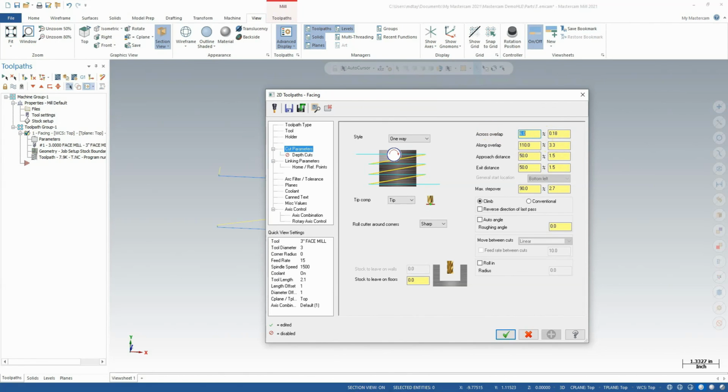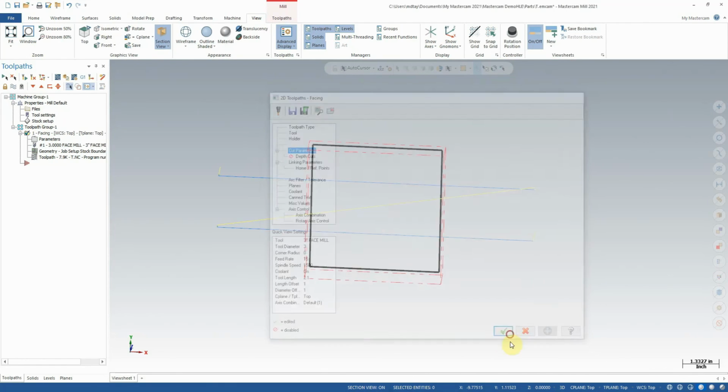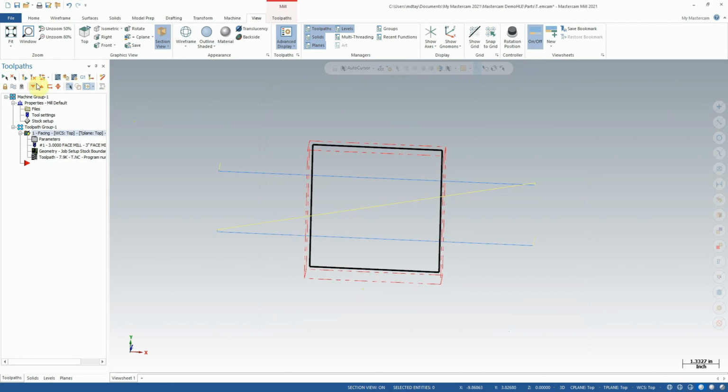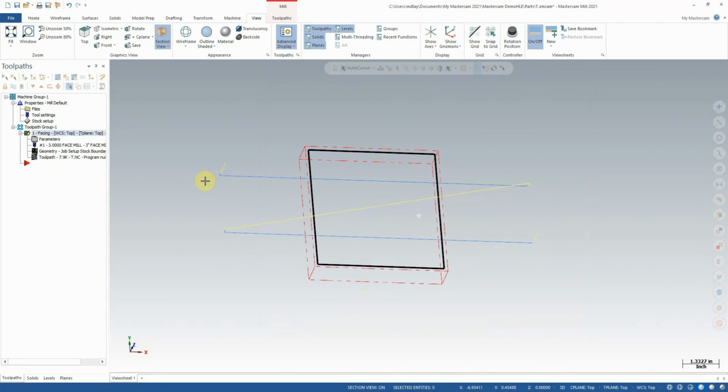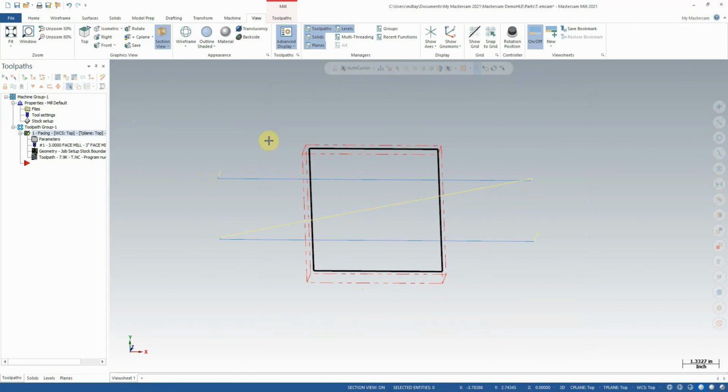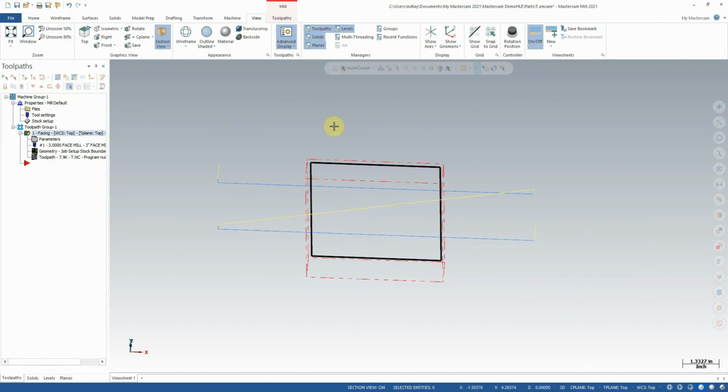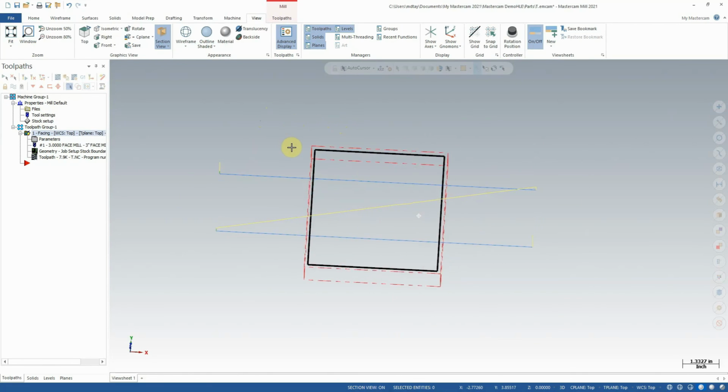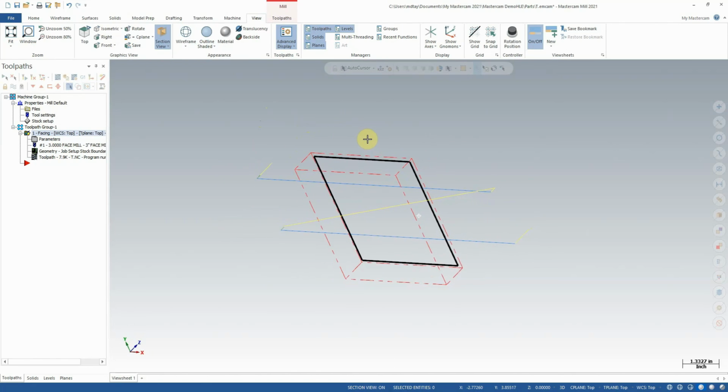So let's set this to 6%, which gives it a 180 thou per side, which still results in less than 5.4 overall, which is our tolerance limit. So let's check that. Now we have 2 cuts finally. So these are the kind of things that can be a little bit tedious to sort out, but knowing the things you can adjust to fix these problems is how you get a result that you're desiring.